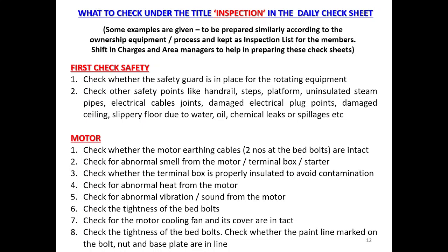Next is the motor. What must we inspect? We must inspect the following. Check whether the motor earthing cables, that is 2 numbers on the bed bolts, are intact and not detached, to ensure safety. Check for abnormal sound emanating from the motor, cable terminal box or starter. Check whether the terminal box is properly insulated to avoid contamination entry.